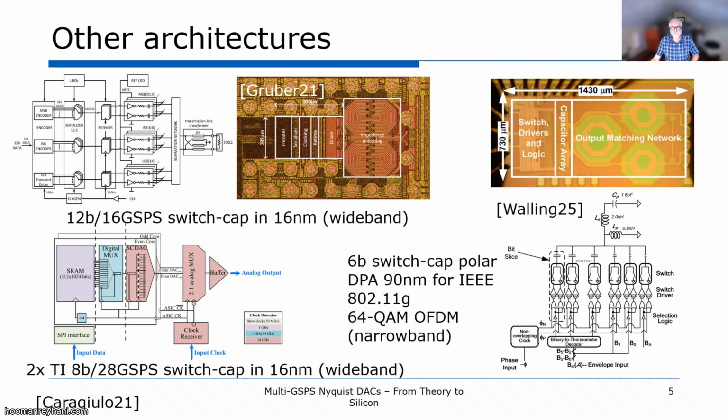On the other hand, many of the inverter-based and charge-sharing emerging architectures get around the voltage headroom problem, but these either require a wideband impedance matching network to be placed before the actual output load, or they require highly linear continuous time buffers, which can be even harder to implement at the DAC itself. You can immediately spot integrated inductors that are bigger than the DACs themselves in some of the die photographs. In the end, it's all about matching the right solution to the problem and about trade-offs.